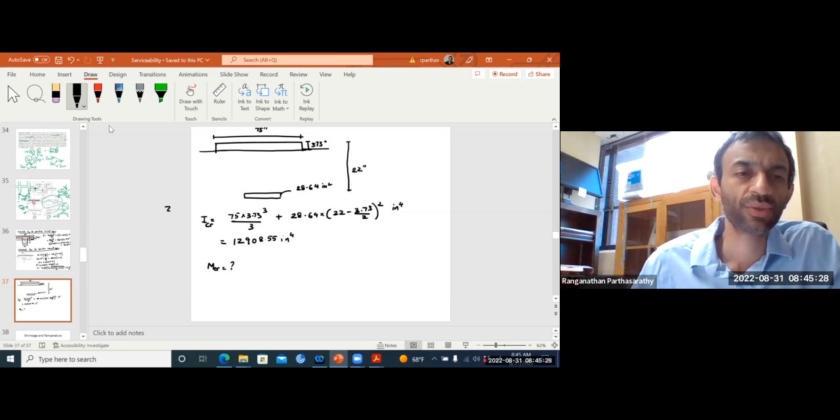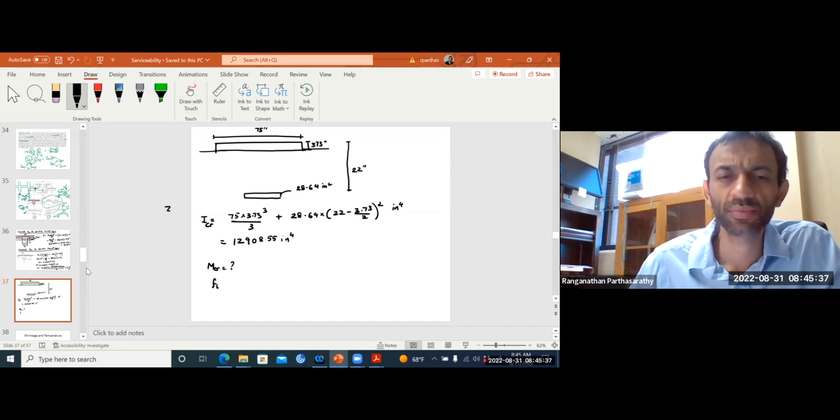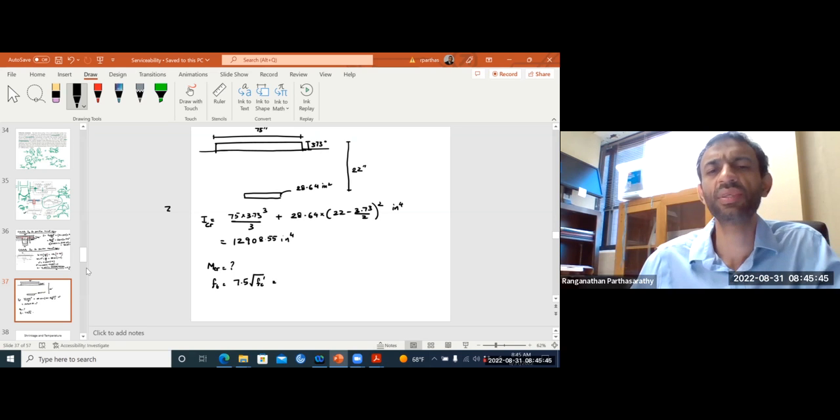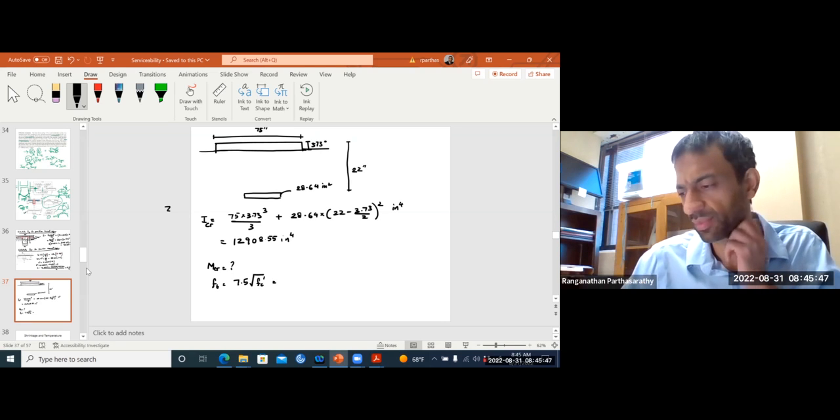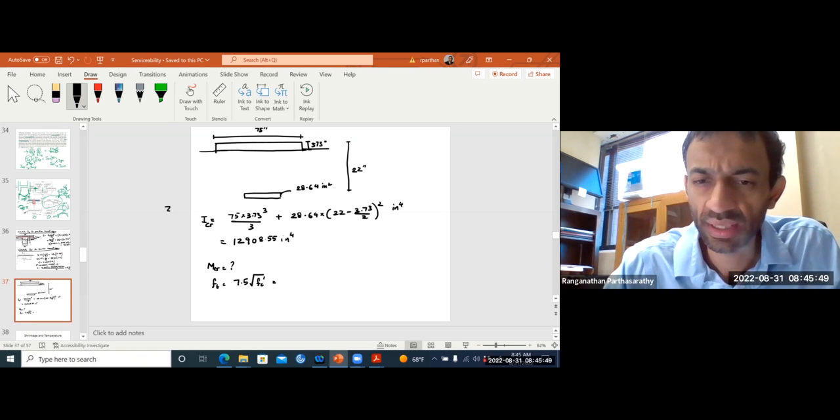How will we determine our cracking moment? What is fr? Does any of you remember directly? The modulus of rupture, 7.5 square root of f'c, right?